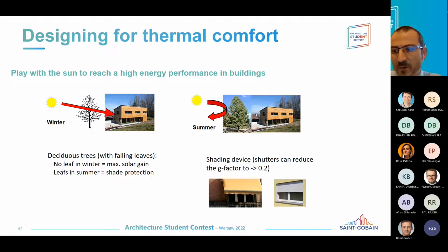So I was saying about these shading devices. They can come in different forms. It can be very well static ones. They can even be part of the design as such. But as well, you can have some ideas here with automatic ones. They can be linked with sensors these days. It's nothing extraordinary to link them to thermal sensors, and this way, of course, they get activated, and by getting activated, they will obturate the view, and therefore you will not get overheating inside of a building, in a space and so on.